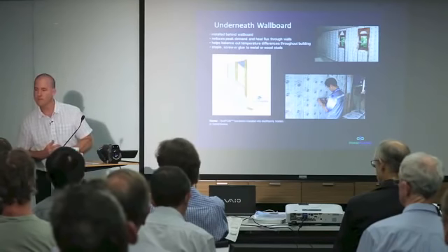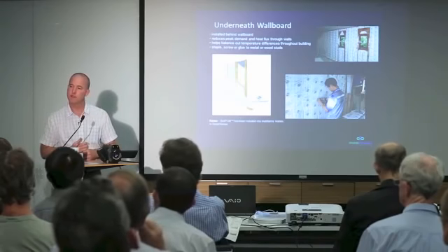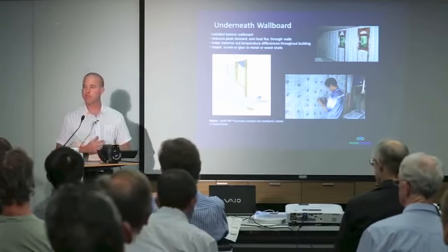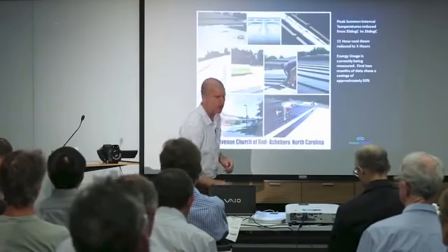What's better, if you had a flat roof, on the top of the roof, underneath the... Okay, the question is, where's the best place to install phase change material? Closest to the people. So in between the plasterboard or the timber lining and the insulation itself. Because you're trying to control and stabilise the internal temperature. You're not trying to control the external temperature.